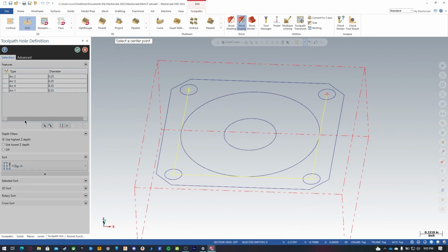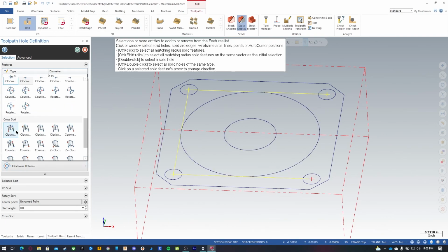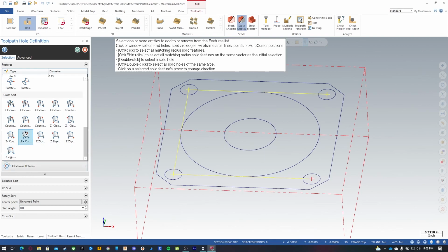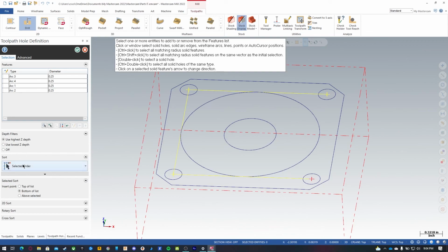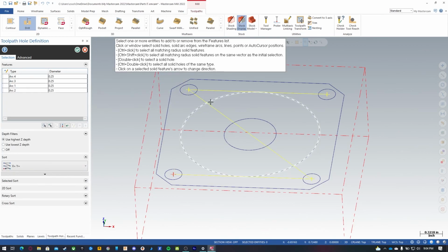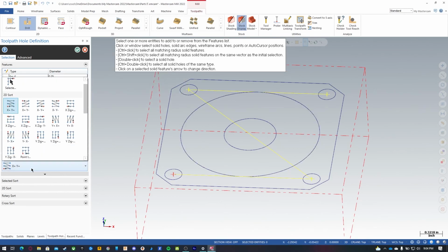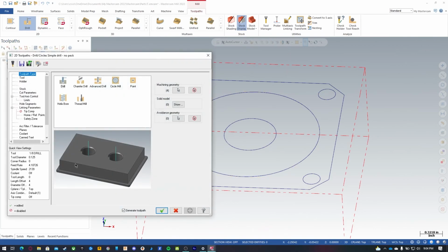So I'll pick this one. So then it can do different assortments. Maybe you need to clear a wall or an island or something. So it's good to have point sorting turned on in certain applications. In this case, we have total clearance on everything, so we don't really need to worry about any huge inefficiencies or tool collisions. So let's click OK.